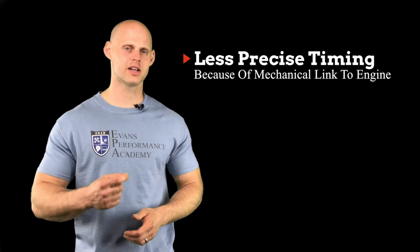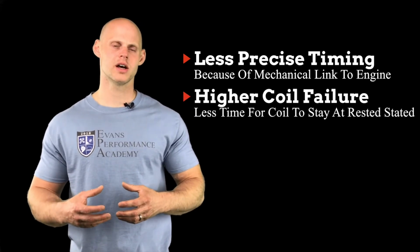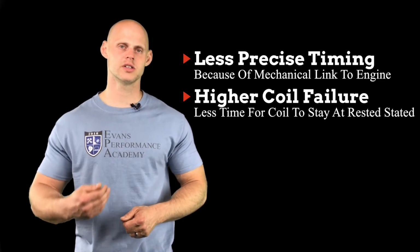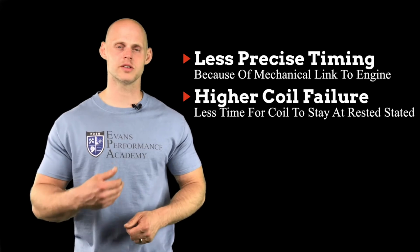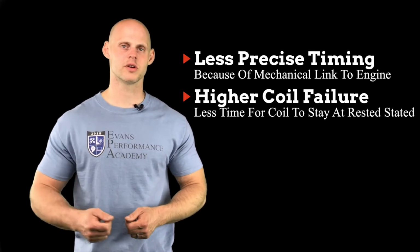Now, the other disadvantage is going to be that our ignition coil is going to have much less cooling time, because we're going to be firing and discharging our ignition coil in the system to provide spark to all the cylinders that have to fire off our distributor cap.